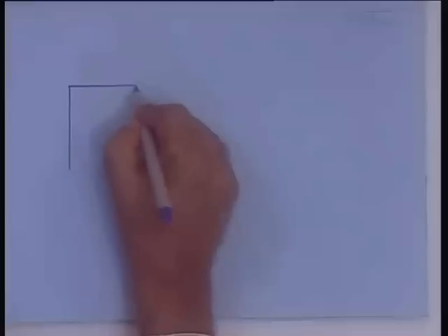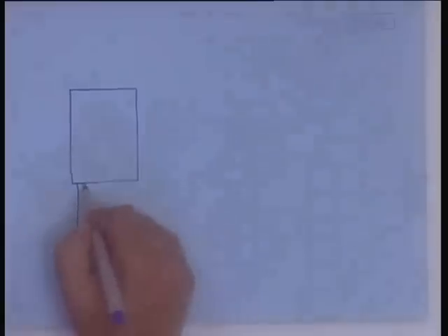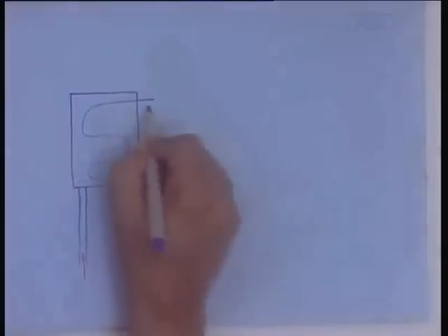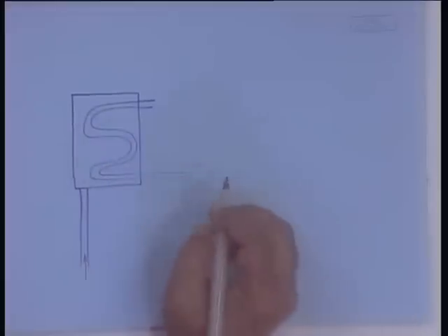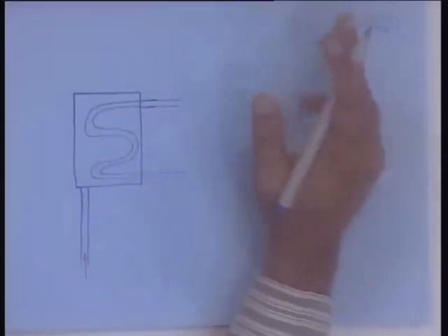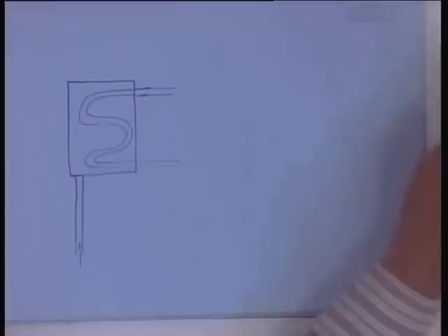So, in case of the binary cycle, how will it look? It will look as if you have a chamber which will act as the boiler, in which your geothermal steam or hot water comes like this. And then you have the boiler for the binary fluid. And in case of the OTEC cycle, we have learned that earlier people used to consider freon as a suitable binary fluid, but nowadays with the problem of the ozone hole, freon is no longer the favored binary fluid. Now most people are considering either ammonia or some newer substance that does not have the ozone hole depletion characteristic.